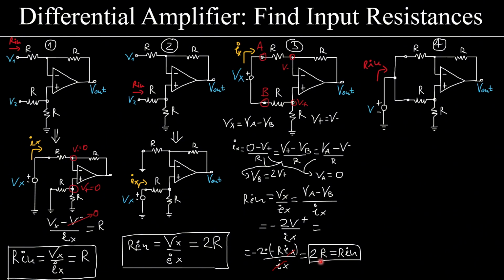In case we had a negative input resistance in an op-amp circuit in general, this would not mean that this is a confirmation of whether we did something right or wrong. So if I find a negative input resistance or a negative output resistance, it would not necessarily mean that I have made a mistake somewhere. This is very possible in op-amp configurations. It can happen that we notice some negative resistance at the input or the output of the circuit. It can happen. This doesn't mean that this is a physically negative resistance.